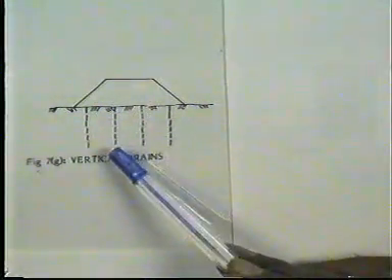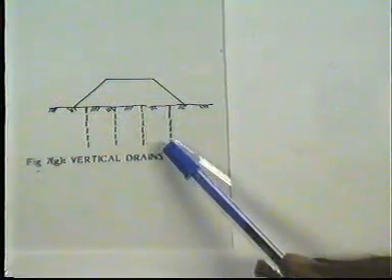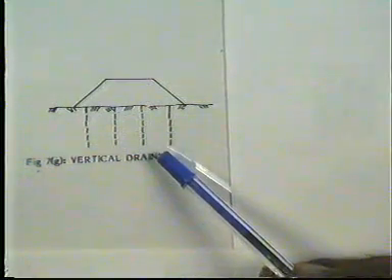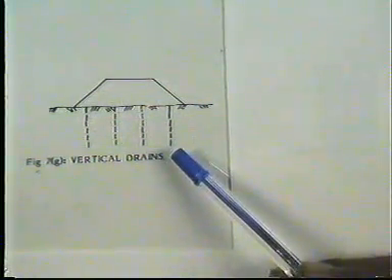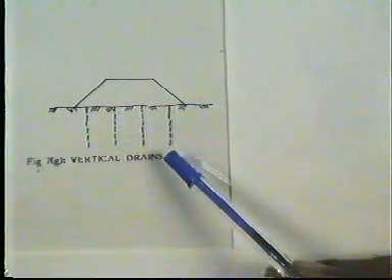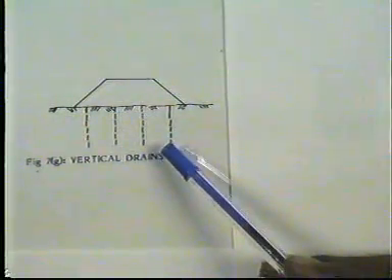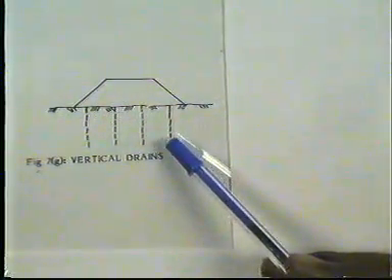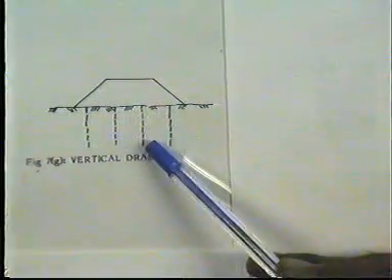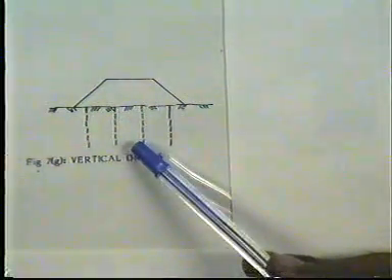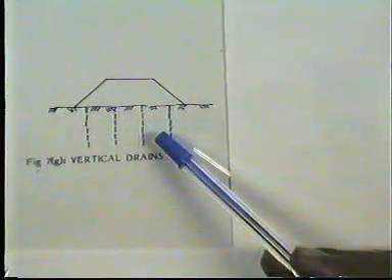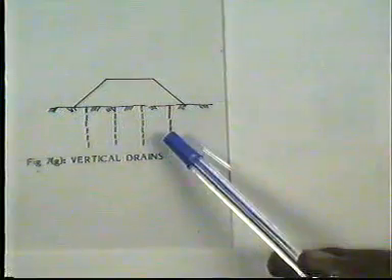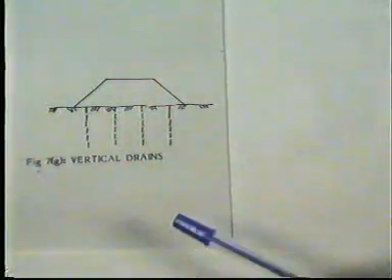Here this geosynthetics material acts as a filter. A geosynthetic functions as a filter when placed in contact with the soil, and it allows the water seeping from the soil to pass through while preventing most soil particles from being carried away by the water current.